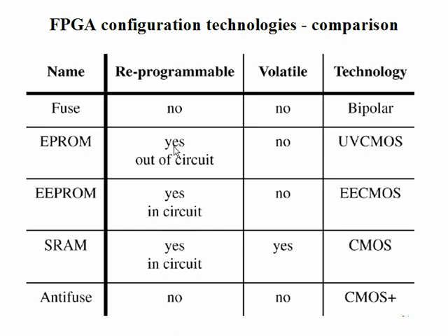SRAM, anti-fuse, flash. SRAM is something you use only for R&D purposes. You never want to make the program permanent on it. Anti-fuse is something you want to program permanently, once, that's all. Flash is something which has the advantages of both. That's the reason the flash based FPGAs are obviously costlier.